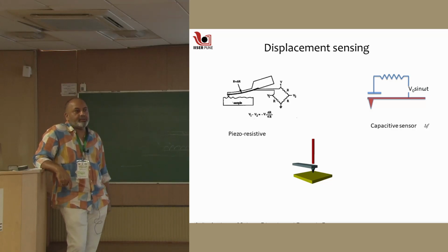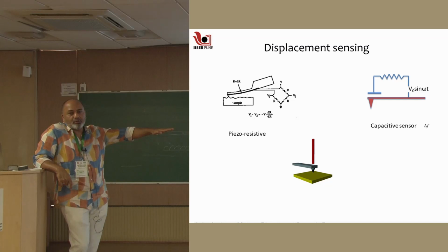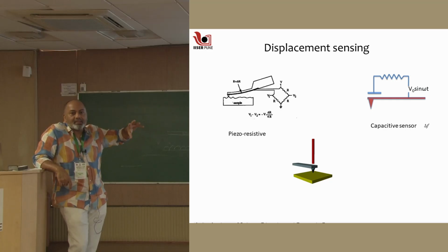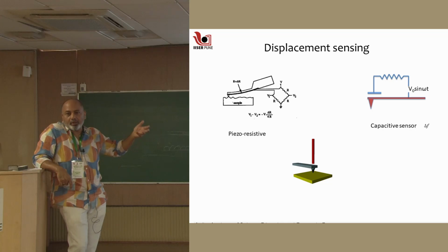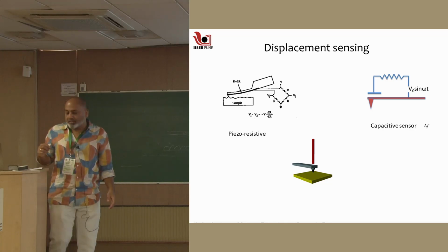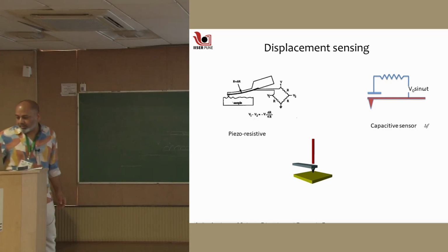detected. I said about 1 Newton per meter cantilever with a nanonewton force will bend by a nanometer displacement. Now typically bending is not in nanometers, right? Bending is an angle, right? You bend by an angle. So when I say bent by a nanometer, what I really mean is this idealized model where the cantilever is really thought of as a spring and the spring is getting stretched by a nanometer. So it is in a schematic way.